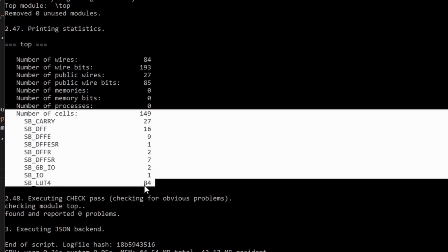Obviously, that is the true number of lookup tables that is used in the FPGA. It's just that if you make another tiny change that maybe you think shouldn't have any effect on the number of lookup tables, and then all of a sudden you see your number of lookup tables go up, it's not your fault. It's just the pseudo-deterministic nature of place and route.